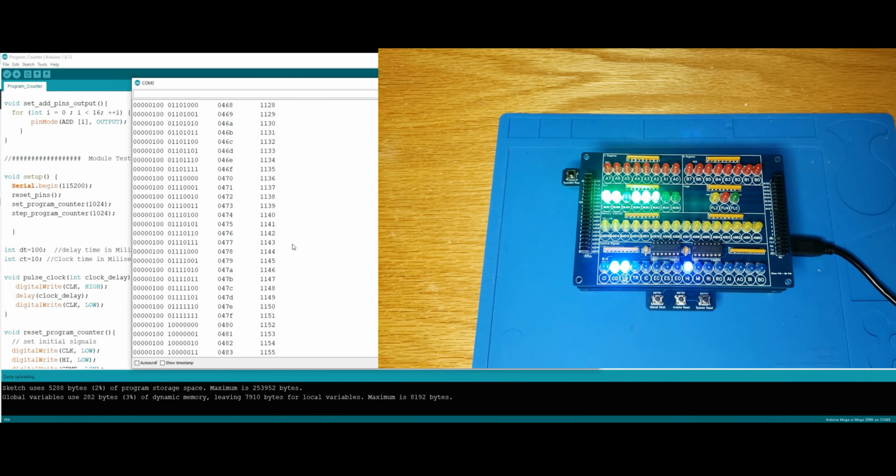Now if you look at the LEDs on an LED board, you notice that the HI signal is actually flashing on and off. So each time the HI signal is low, we are basically reading the low byte. And each time the HI signal is high and the LED comes up on the LED board, that means that we are actually reading the high byte.